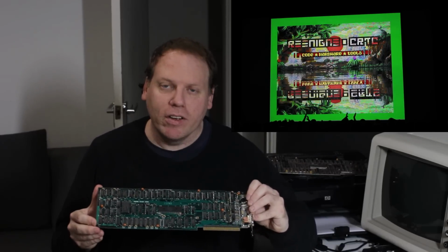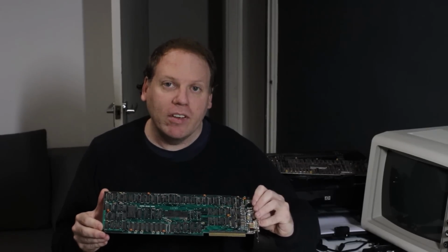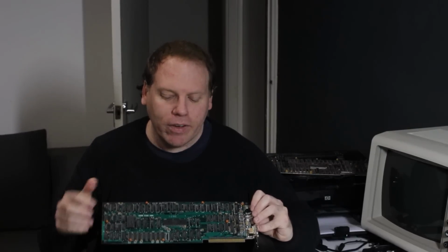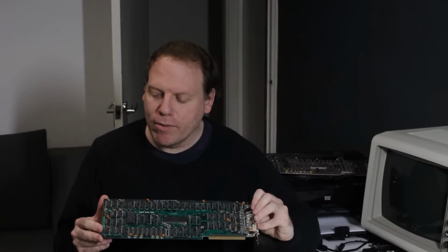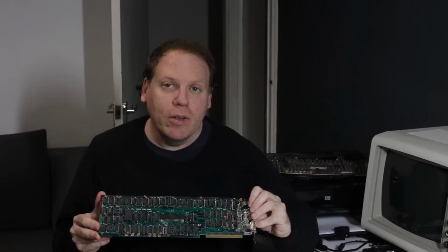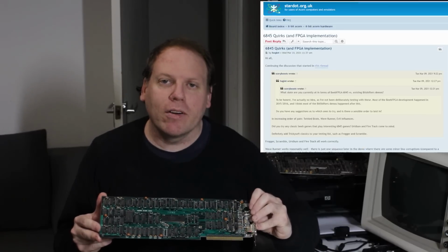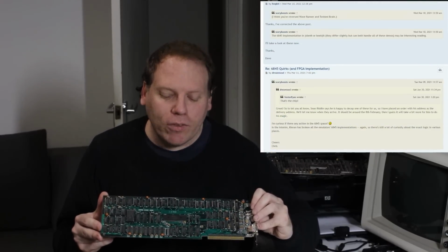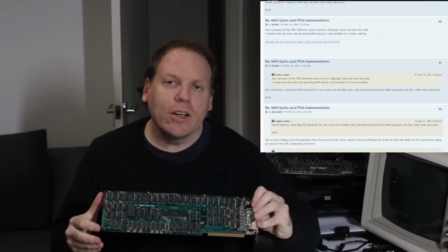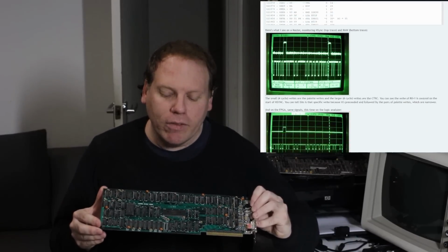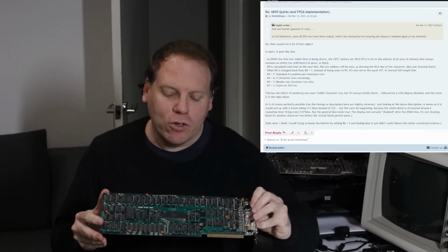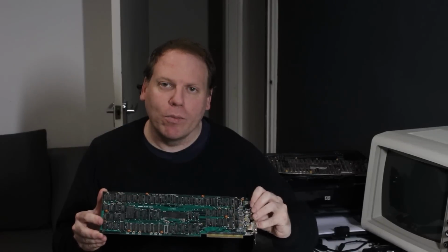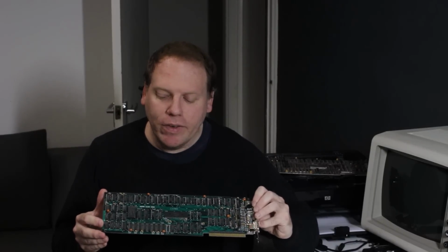There's two that I commonly see on this card, the original Motorola MC6845 and a Hitachi clone of that, which is used here, the HD6845. And on other similar era CGA cards, you'll also find a UM6845. But there are rumours amongst other communities that use these, for example the BBC Micro and the Amstrad CPC 464 communities, that you can get even finer control by register writes of this chip down to the cycle accurate level. And maybe you can even get control down to a partial character level, which I'll explain the importance of a little later in the video.